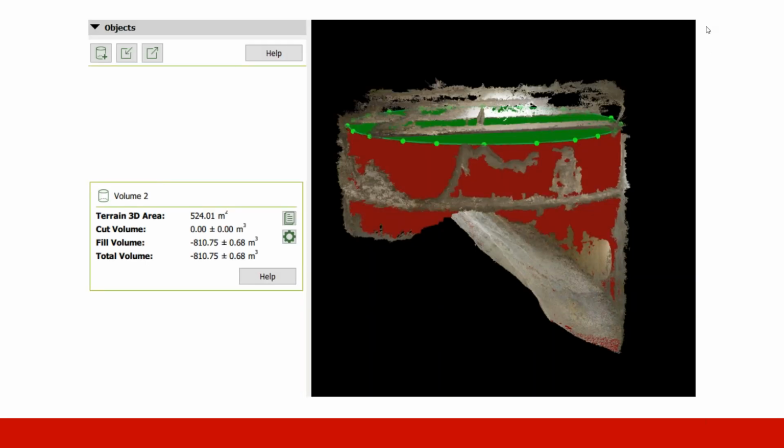So this is what the interface looks like. You can click around and then basically extrude this surface down onto the surface of the material, and that's going to give you the volume of this negative space in the top of the silo, basically. So this indicates that in order to completely fill this one, you would have to add 810 cubic meters. And the reason we do it top down is these usually taper down into a cone at the bottom.